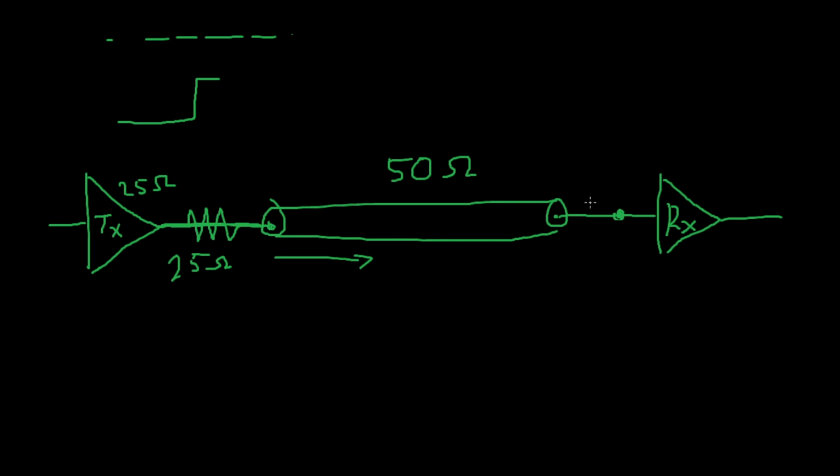Whenever it hits the other end, we've got exactly half VCC here because of what we discussed earlier with 50 ohm source and 50 ohm load from our transmission line. But whenever this signal gets to the distant end, it no longer sees 50 ohms, it suddenly sees high impedance. Whenever it sees that high impedance, it reflects. And what you're going to end up seeing is that that half waveform jumps up to a full waveform. So you end up going from 0 all the way to VCC, and it has a nice smooth transition.